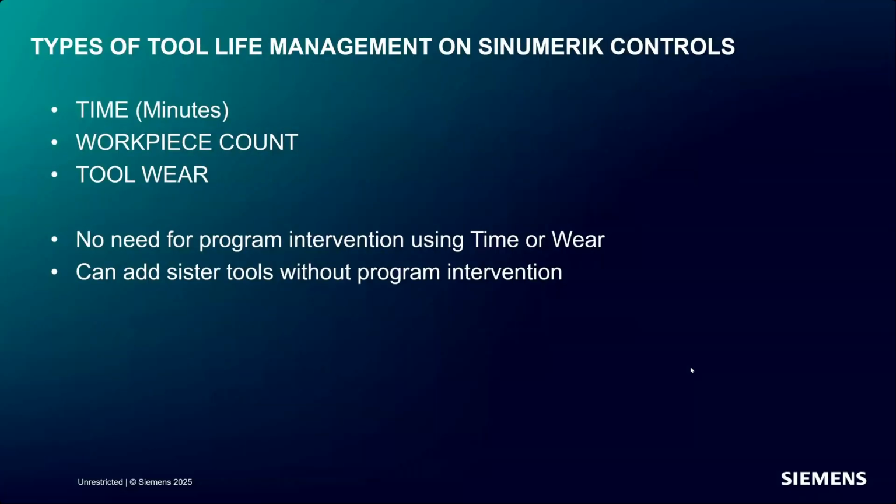So now I want to step over into my virtual machine, and I want to take you through what tool life management looks like on a Sinumerik control. We have 3 ways that we can set it up. We can use time, which is in minutes. We can use workpiece count, and we can use tool wear.